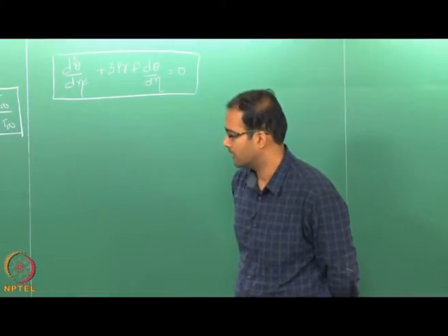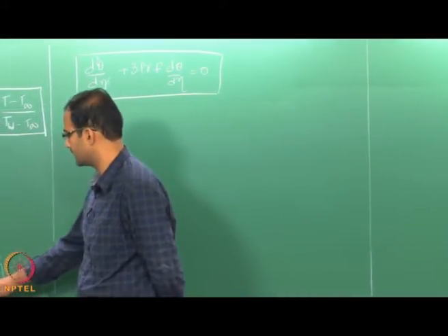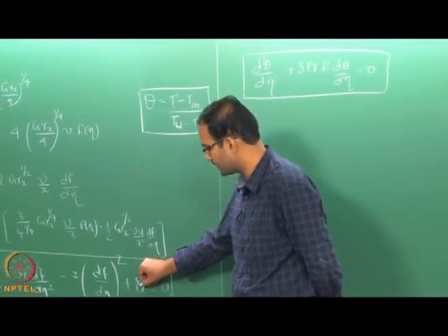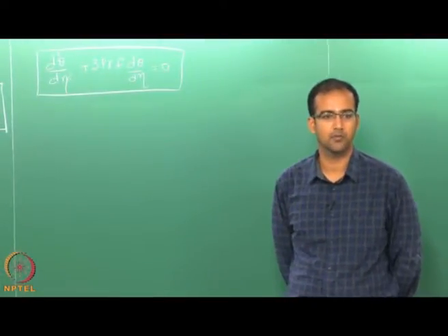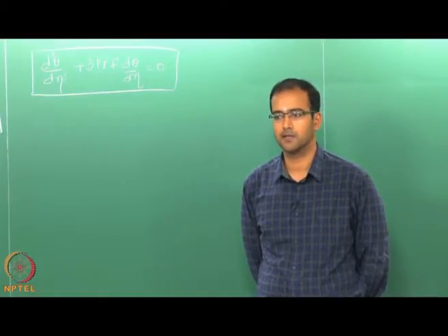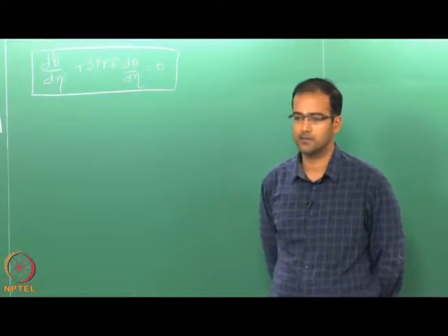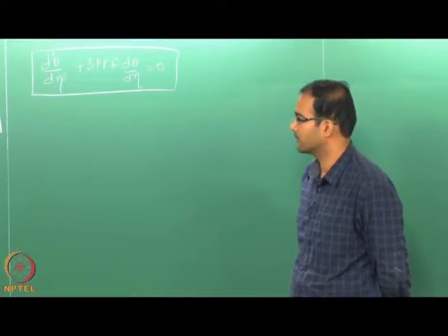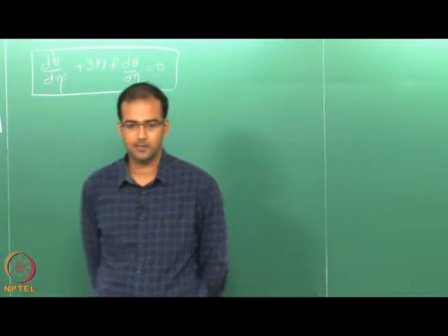Now you should understand that these two equations are coupled in the sense that you have this term theta sitting in the momentum equation, and therefore, unlike the external forced convection case, you cannot solve them separately. You have to do this simultaneously when you use the shooting method, and we will see that in a short time. But before that, I asked you to check whether you get these similarity equations.